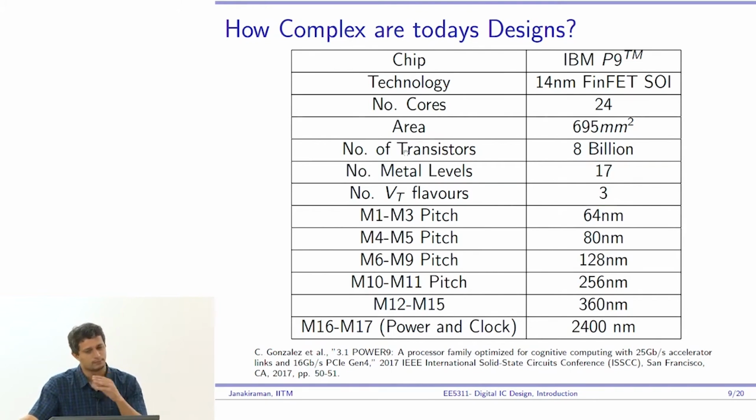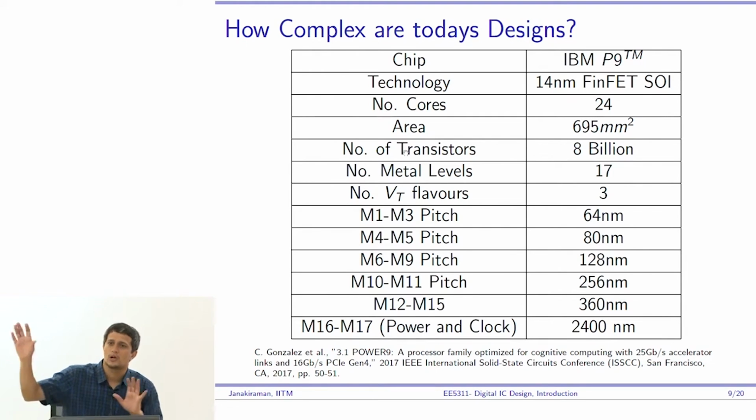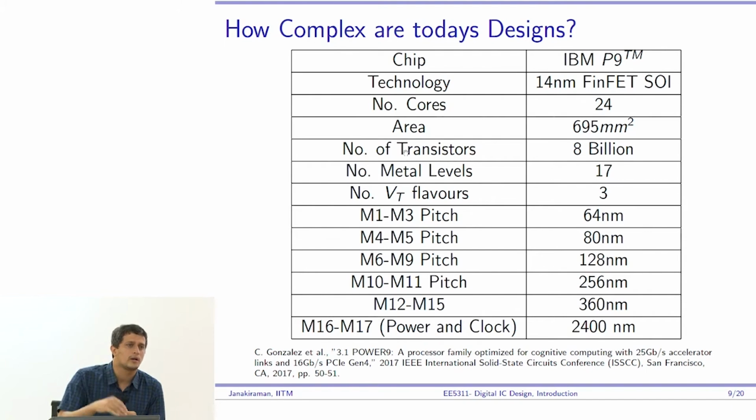FinFET again was introduced only in 14 nanometer. Up to 22 nanometer, the transistors were just scaled down regularly, okay, and they were able to achieve their targets without much problem. But beyond 22 nanometer, it became difficult to contain the leakage current, right? Keeping the on current, this thing. So just an order of magnitude question, if the on current is, let's say, 1 unit, what will be the off current like? Order of magnitude.